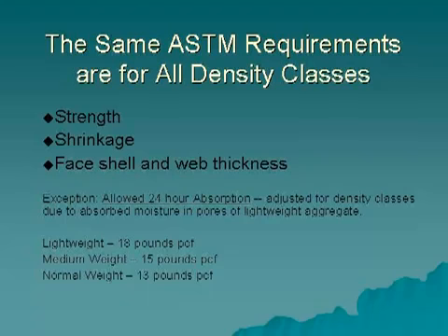When block manufacturers started manufacturing lightweight block intended for load-bearing applications, it was apparent that the limit for absorbed water determined by the lab test would need, of course, to be increased. Why? Because lightweight aggregate, as described in ASTM C331, itself absorbs water.